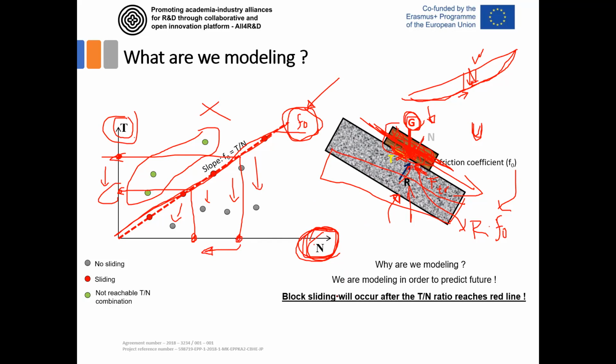The same thing is happening in the soil mass, because without water you have this self weight, and when the water comes here, this component is reduced. The self weight, actually, we call it effective stress. It's called effective stress. That is actually a stress, total stress minus pore pressure.